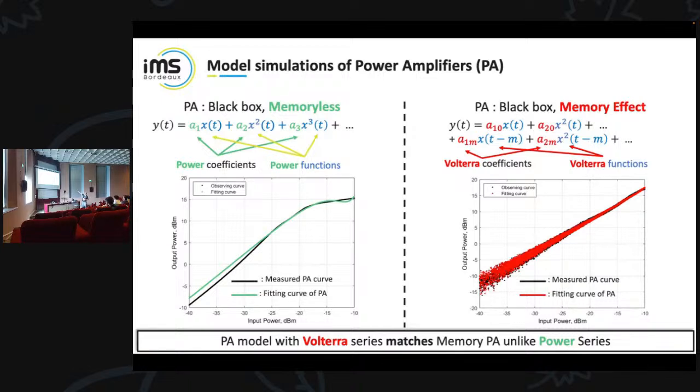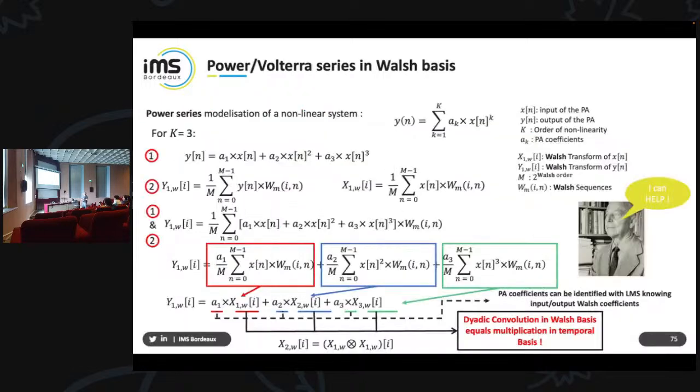On the left, with this curve. And then on the right, we will observe how the characteristic is going to be modified. That's why you have a cloud of dots there. It's because it's an in-between, like a Monte Carlo simulation you have for your PA. And what you want to do is get just a straight line. On top of it, it's more and more complex.